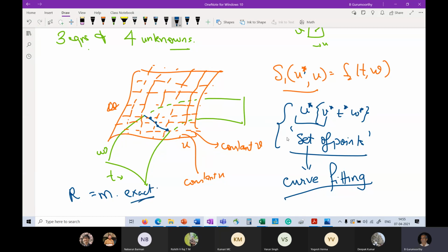That when my number of control points for the curve is the same as the number of input points on the curve, I'll get an exact solution. But when you're doing intersection, you will do 100 curves in one direction and 100 curves in the other direction, which means potentially you can get 150 to 160 points. You're not going to have a control polygon of 150 points. So typically in all these cases, you will find that R is not as great as in scanning, but definitely it is greater. And therefore, what is the implication of that?